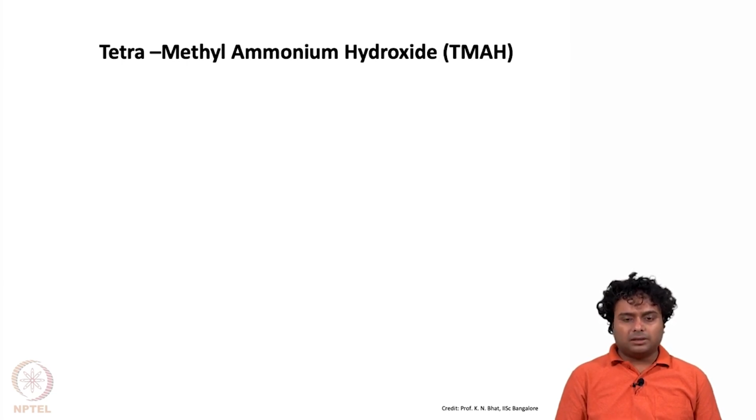As you understand by now, the etching rate depends on the silicon crystallinity, or which direction we are etching. So changing the chemical, that property does not change. That means the 100 will have a medium kind of etching rate, 110 will have the highest etching rate, and 111 will have the lowest etching rate. But in those directions, the magnitude of the etching rate will definitely change with different kinds of chemicals.